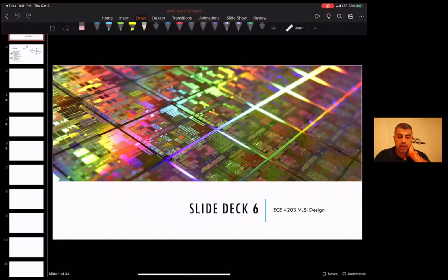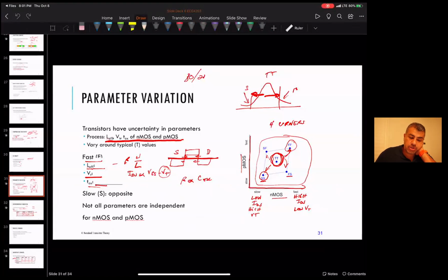So if you remember this slide from the previous lecture, basically the manufacturer has some variability in how they manufacture the stuff. And maybe this makes more sense now, because look at what they're saying: what can change is the threshold voltage, Tox, L effective. All these things are changing our IDSs for N versus P, from chip to chip, from wafer to wafer, from wafer run to wafer run.